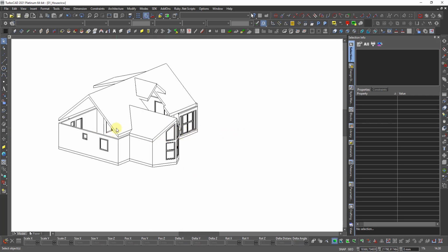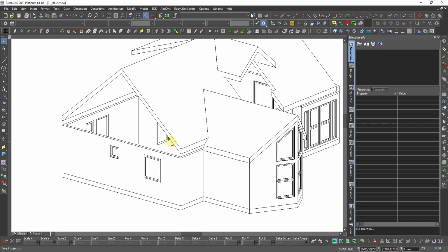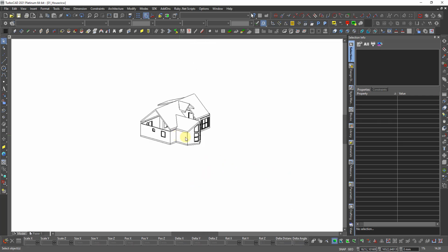Change the wall style, so that the foundation wall, where they're coming down here, is not on the same level out as the cladding wall. Put it that way. This should be 54mm more outside than the foundation. So then we can do that. We can make a copy of the style.